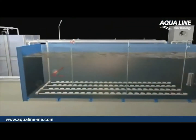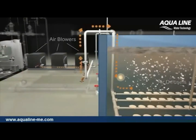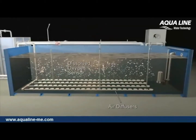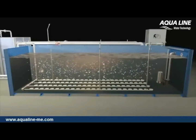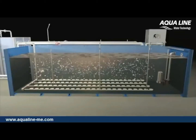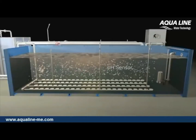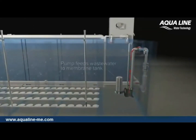Oxygen is supplied using air blowers and a diffused aeration system. A dissolved oxygen sensor monitors the selected range to help the operator maintain nitrification in the removal of organic material. In this oxygen-rich environment, organic material and ammonia nitrogen are biologically oxidized to carbon dioxide, nitrate, and water. A pH sensor is provided in the aeration tank for continuous monitoring of the pH condition. From the aerobic tank, mixed liquor is pumped to the membrane filtration tank for liquid-solid separation.